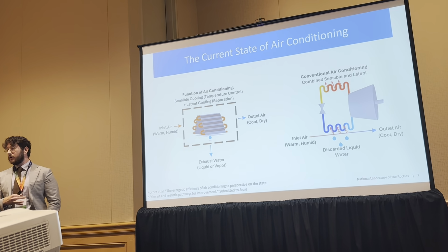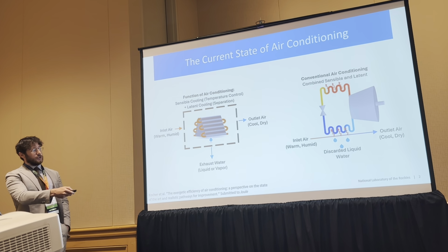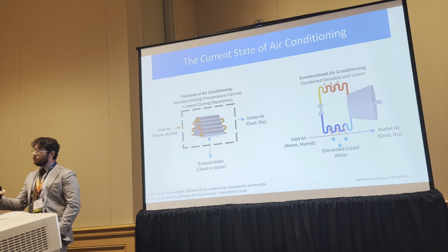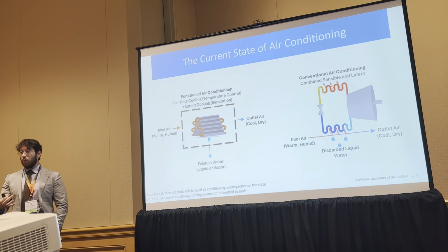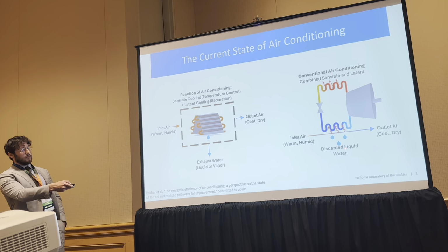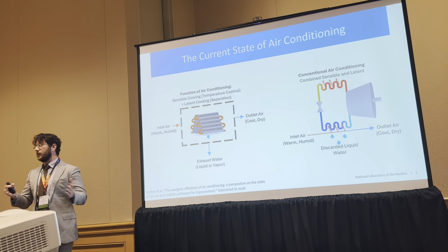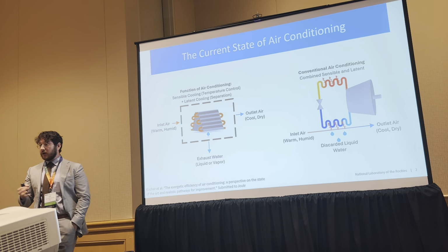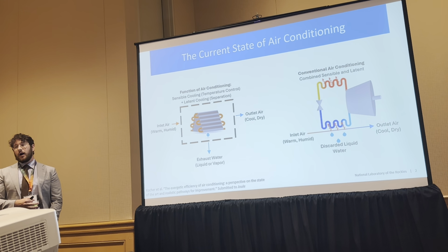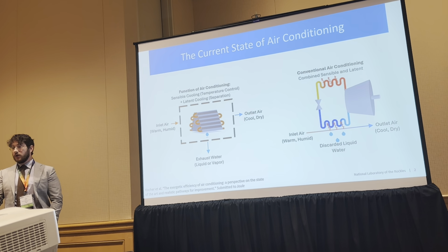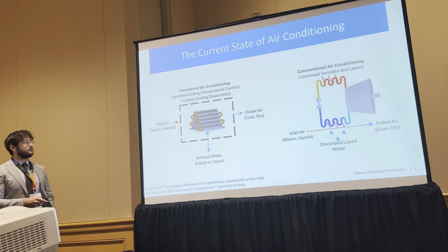And at that evaporator, you've got cold refrigerant, which is cooling off the air that you're going to provide to your building, but it's actually overcooling it to a lower temperature than you want, just in terms of thermal comfort, for the sake of condensing that moisture out of the air to get your separation or your dehumidification. So it's not very efficient because you're overcooling your air, but it is really convenient, and that's why almost every air conditioner in the world uses this system architecture.